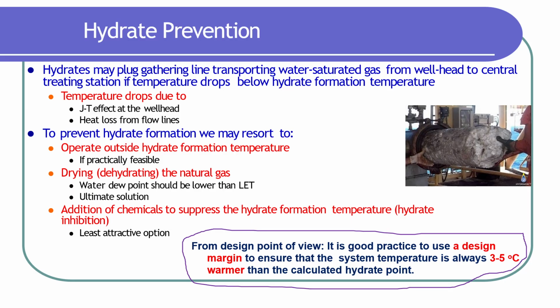So normally, the scenario is where you have, for example, a temperature drop, because you have to keep in mind that we said that the two optimum conditions for the hydrate formation are high pressure and very low temperature. So normally, when you transport the gas from the gathering station, for example, to the on-field processing station, or to the on-field plant, you might experience a pressure or temperature drop, and this temperature drop will contribute, or will provide a good condition for the hydrate to start forming.